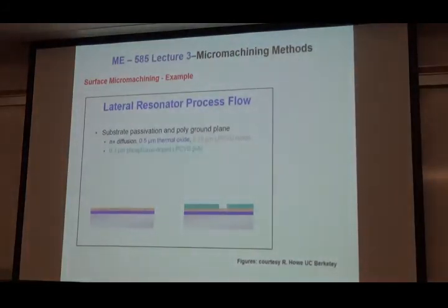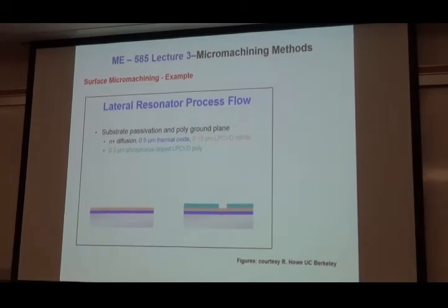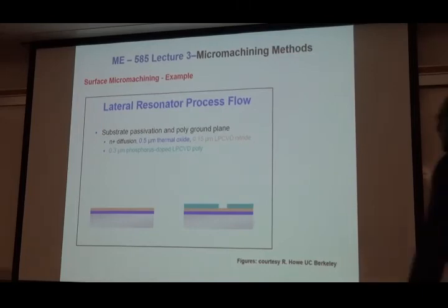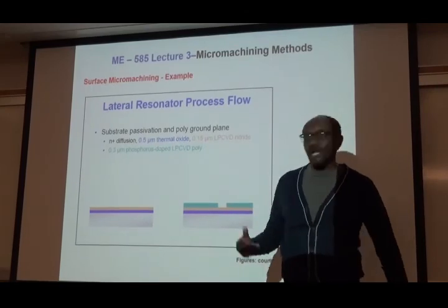The reason is most of the stuff that we make are electrostatic devices, so they store a lot of charge. And if they are in excess, you don't want those charges to go through the wafer. So you put excess charge already. It's just like the way we fight with fire sometimes, right? You set fire ahead of it and then remove the material. Essentially you diffuse with N+, so you have excess electrons, so you're not going to push additional electrons.